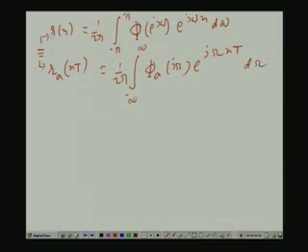Now, the two left hand sides are equal, that you have seen. So, that means by equating the two right hand sides, we can try to derive a relation between the two power spectral densities. One of them is the PSD for the discrete sequence, another is the PSD for the original analog random process. Okay. Now, the second integral you can break down like this.